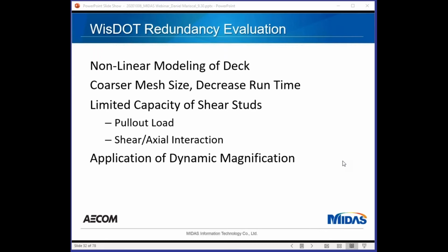Eventually, we decided to use plate elements. We did some tests to make sure that, number one, the plate elements could have reinforcement elements attached to them, which they could, and that the total concrete strain model could be used, which it could.